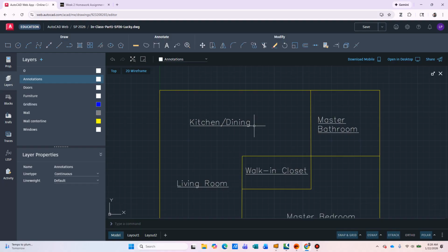So that means when we're doing the offset for our floor plan, we're going to offset the center line 4 inches outside and 4 inches inside. Then we get the 8 inches wall thickness. So that's what we're going to do using the offset function.